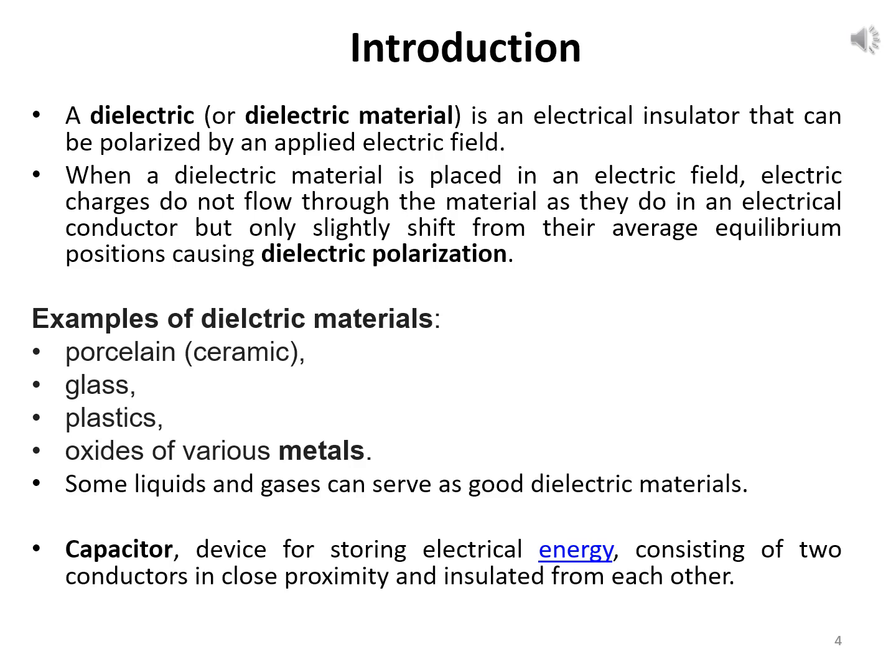So what limits the amount of charge that can be stored on a capacitor? We can say that the voltage can be increased, but electric breakdown will occur if the electric field inside the capacitor becomes too large. The capacity of capacitors can be increased by expanding the electrode areas and by reducing the gap between the electrodes.